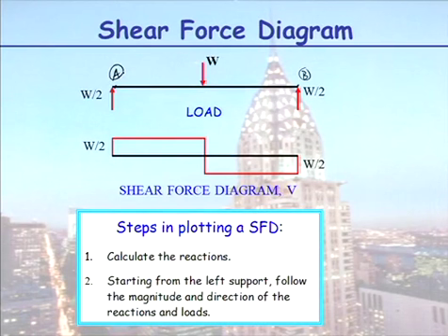Okay, you start at the left-hand end. You follow the vertical loads in this case for a horizontal beam. We step up. When we have no load change, we just move horizontally across. We step down wherever we have a load, we move horizontally across.